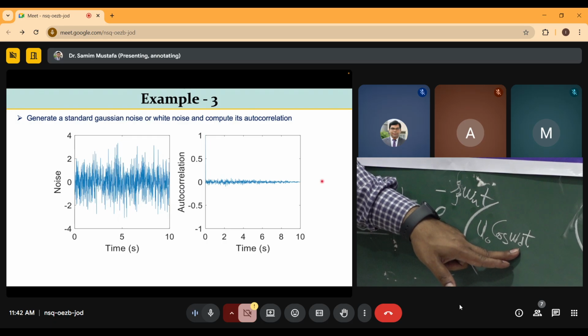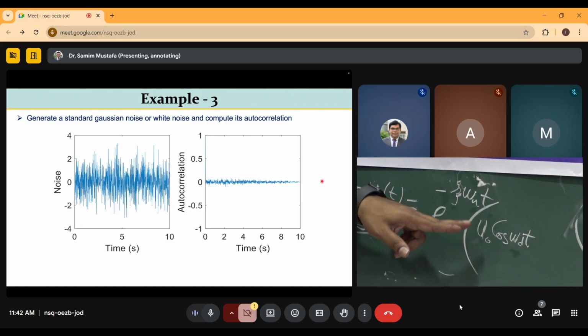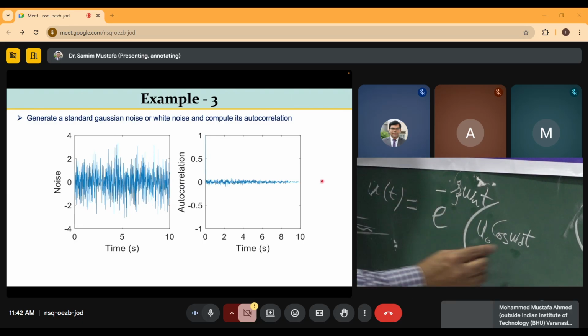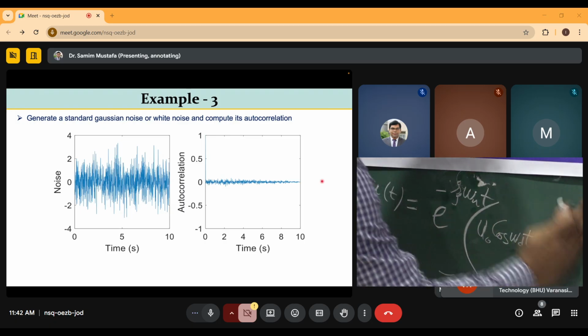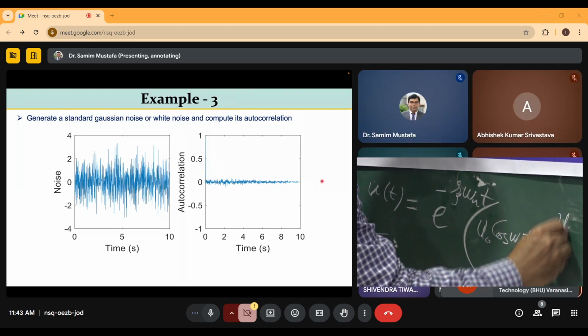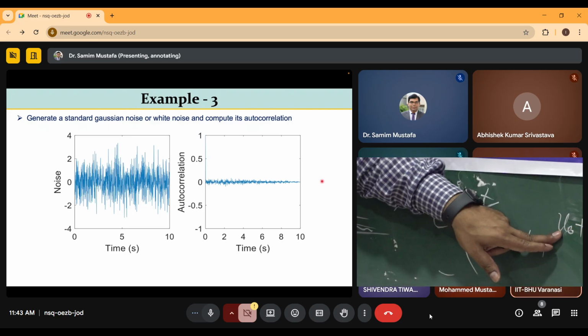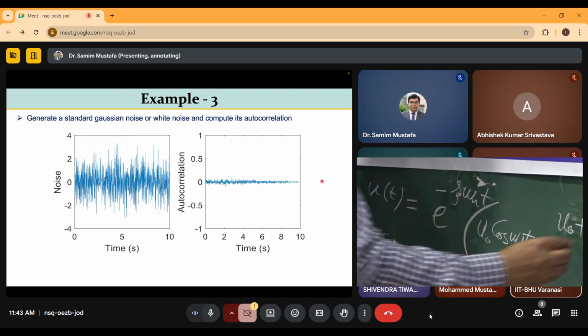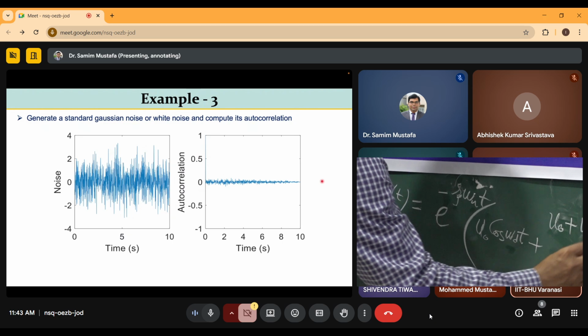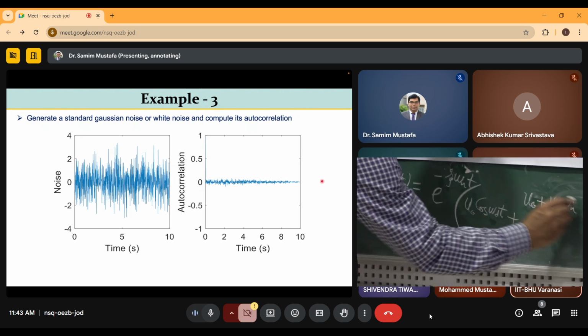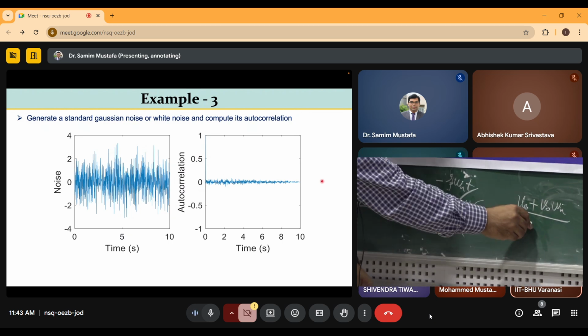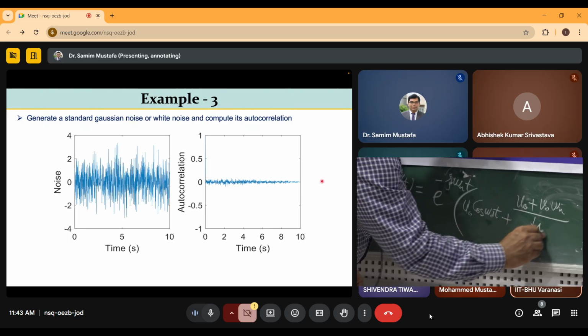The damped natural frequency is omega_n times the square root of 1 minus xi squared. Plus there is another term with u_0 and p_0, the initial displacement and initial velocity, then omega_n, and then something with omega_d.